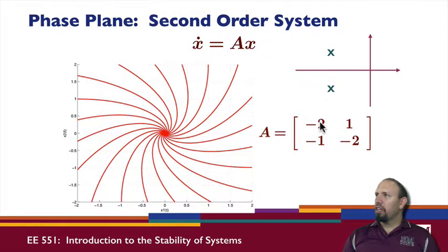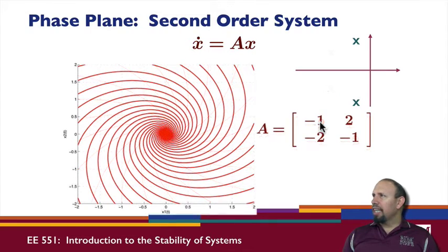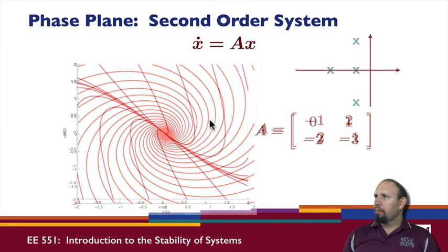What happens if we have it the other way around? What happens if the imaginary part is faster than the real part? Like this. Well, that means it converges, but it converges slowly, and since the frequency is fast, it's able to spiral more as it goes in. Okay, so we get a more oscillatory response in that case.